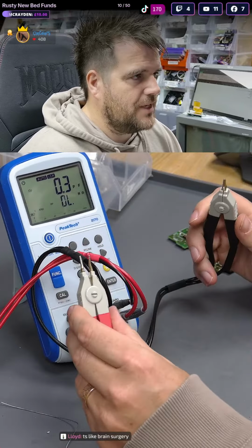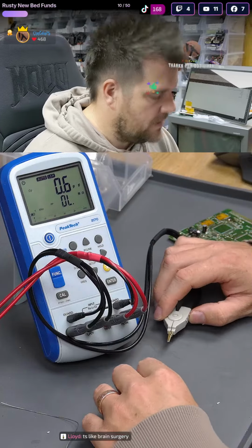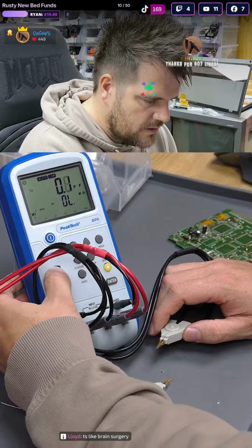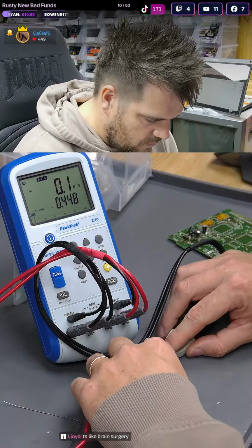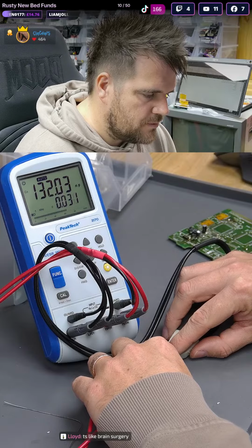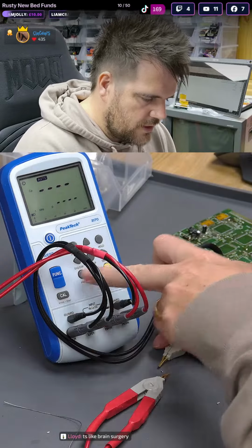I've done it before, so you can just grab over the component like this, but you actually need to use both ends here. So if we tap over here, we'll tell it it's a cap, give it a helping hand, so we're not waiting for it to auto calibrate. If it's a small cap, the frequency won't matter too much. So that's saying 130 nanofarad at 1 kilohertz. So we'll change the frequency.